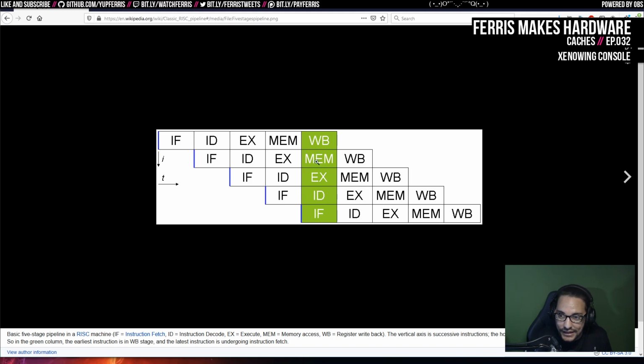Eventually, I do want to put a data cache on here too, but I'm going to start with this kind of read-only instruction fetch cache, which ends up being similar, at least in functionality, to the texture caches, which are also kind of read-only, but sometimes you invalidate them.